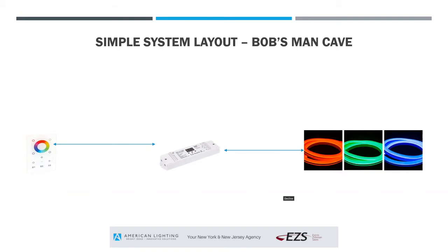That line is generally going to be your DMX cable. So you've got DMX cable running from your controller into the decoder, and then from the decoder, you're running out to your fixture itself. You may not need the decoder. If this was a fixture, a floodlight fixture, you might go DMX straight to that fixture. But again, very simple, easy to use.